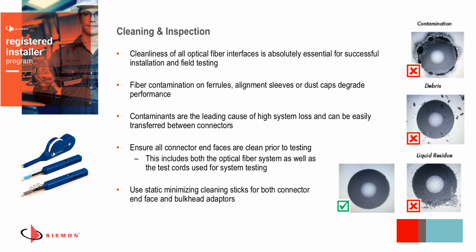So you can have contamination on the actual ferrules, the fibers themselves, the alignment sleeves, and even the dust caps. When something comes from the factory, even though it's been cleaned and polished, the dust caps over time can have an impact on that. Every time you remove a dust cap, or more importantly, every time you're about to mate a fiber into an adapter plate to mate with another fiber, you really need to inspect those end faces to make sure they're properly cleaned. Contaminants just come up time and time again. So inspecting those prior to testing, prior to mating, is very critical.